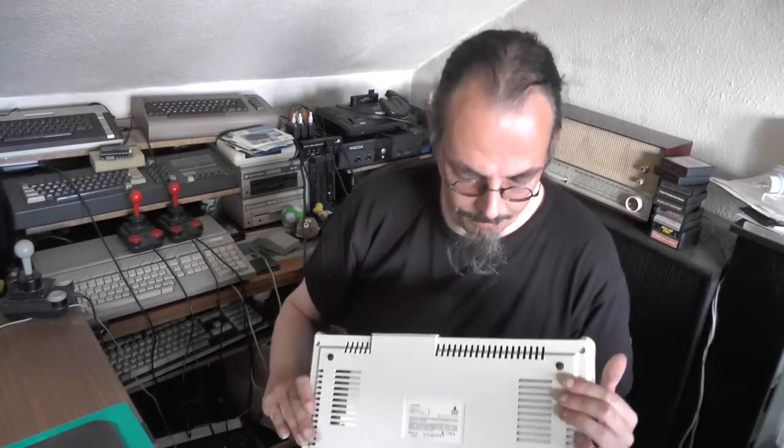Sound comes from the Pokey chip, which, yeah, I like the sound of the Pokey chip, especially for sound effects. It has 4 channels at 8-bit precision, and you can combine 2 channels to get a 16-bit precision. At 8-bit precision, if you use it for music, the music is a little bit out of key, because you only have 256 different frequencies you can select, and they do not always match the note you want to play, so you have to take the nearest.